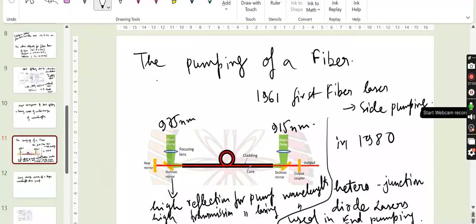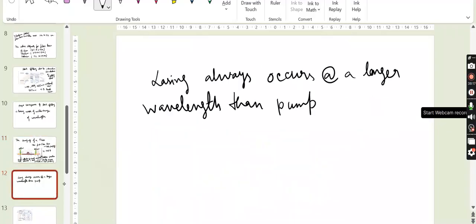So the long fiber is therefore coiled so that it fits a conventionally sized enclosure. The ends of the fiber are anti-reflection coated to avoid intracavity loss through Fresnel reflection. The optical cavity formed with such an external mirror is, however, quite prone to becoming misaligned due to thermal changes or the presence of physical bumps in the fiber that are inevitable.